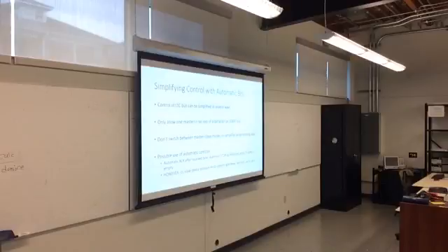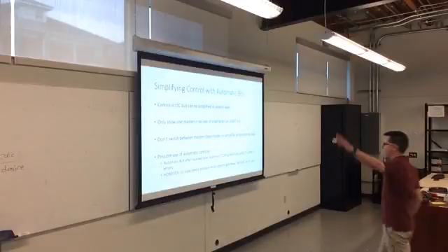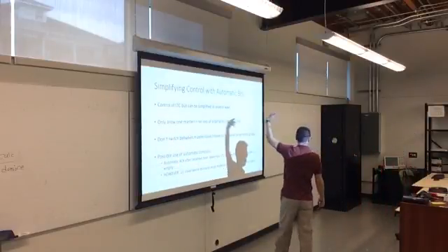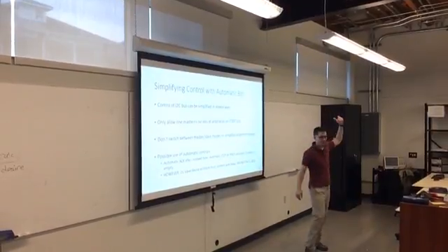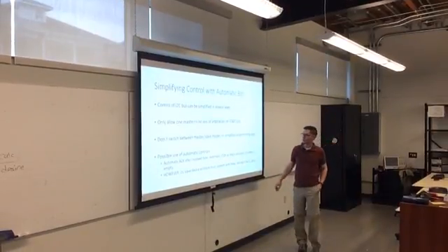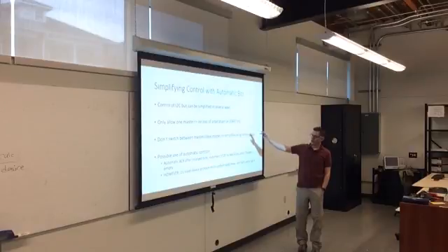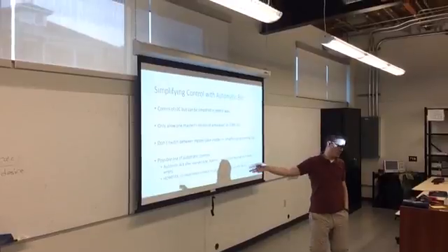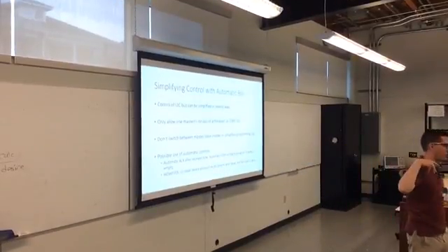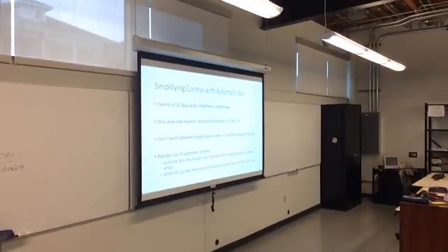The second thing that you can do is something called automatic controls. I put this in here because it's a feature that should automatically send those ACK and NAC and start and stop bits for you. It's supposed to simplify things. However, you have to make sure that your device conforms to those automatic controls. We're not going to use the automatic controls because the accelerometer is not necessarily going to conform to that specification.